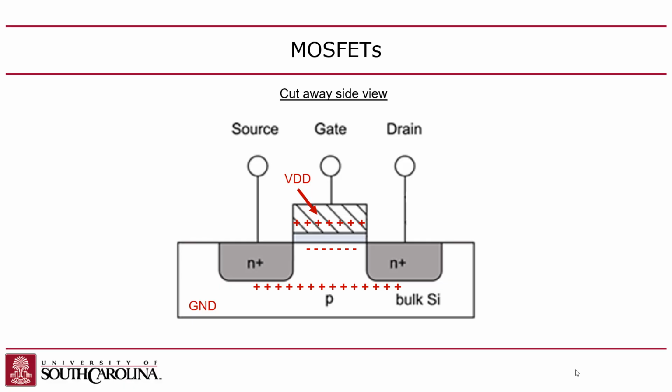So you end up with a gradient of voltages there, right? Now, the problem is that if this transistor has a very high voltage difference between its source and drain, this weird thing happens where, let's say the source is really low and the drain is high, you'll have a different potential along this channel relative to the gate, right? And if the voltage difference between the source and drain is high enough, it'll actually pinch off the channel. But I'll talk more about that in a minute, just keep that in mind.